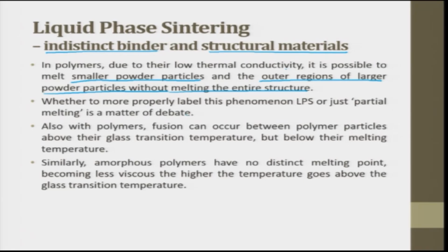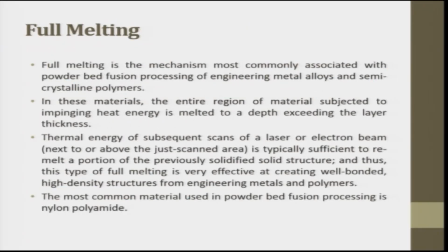Also, with polymers, fusion can occur between the polymer particles above the glass transition temperature but below their melting temperature. With polymer, you have solid state, then glass transition temperature, and then you go to the liquid state. Similarly, amorphous polymers have no distinct melting point, becoming less viscous the higher the temperature goes above the glass transition temperature. The last one is full melting.